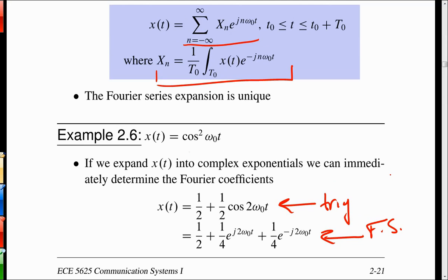All I have to do is just look, compare this up to here, and they sort of should pop off the page at you. You can see omega naught is there. All I have present in this waveform is the fundamental. All I have present in the waveform is a constant, which is the DC term. So that one must be x0.